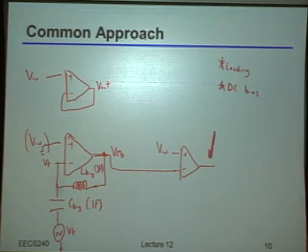Yeah, it's the output, right? Because notice the output is totally open loop. It's not necessarily driving anything else. And if there's any interaction there, then it's not going to be quite right. So in particular, if you have, for example, a CGD or just some feed-forward path there, then indeed you will not be mimicking the loading exactly correctly. Now, it turns out what I've drawn here is usually pretty good, in that as long as you don't have very big feed-forward, you can get very close to the ideal result. But nonetheless, it's never really quite perfect.